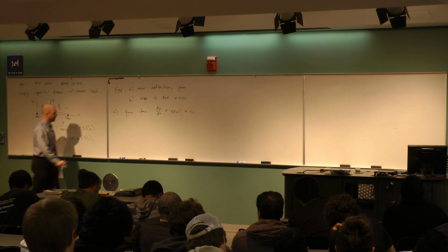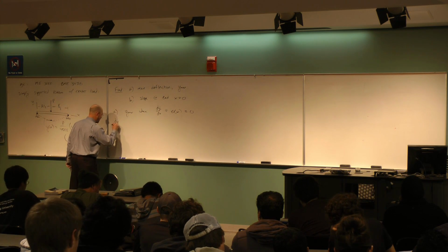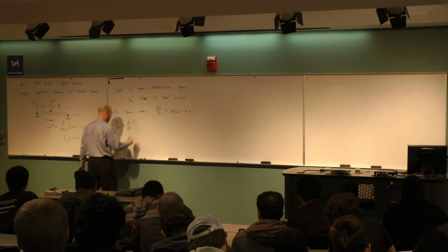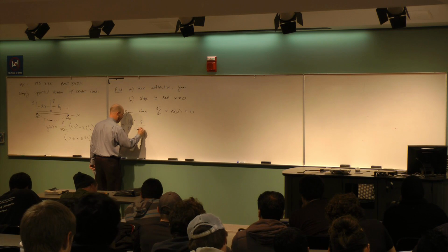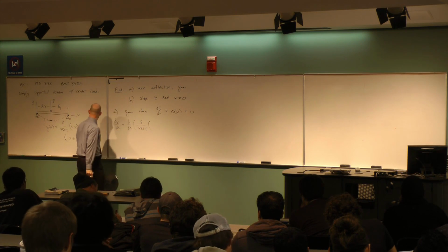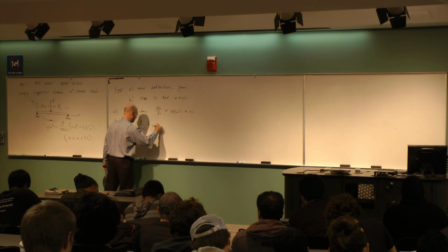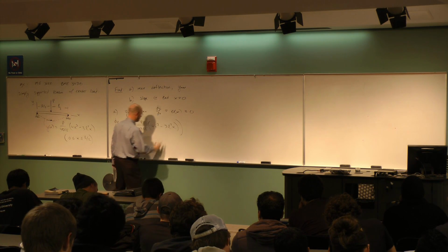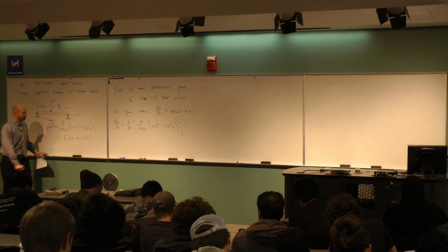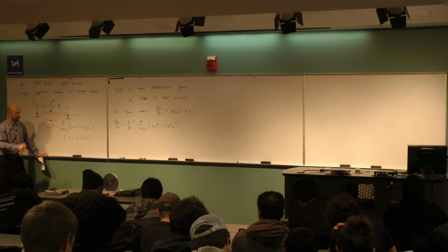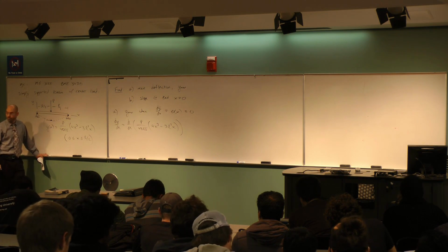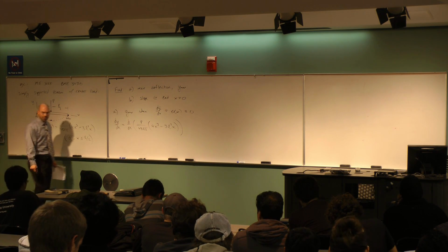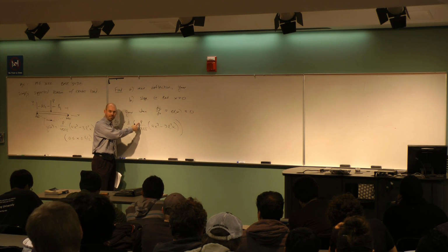So first thing I need then is dy/dx. So I want the derivative with respect to x of this entire guy here, P divided by 48EI, and then I've got 4x cubed minus 3L squared times x. So help me out here. What do I do with the letters out in front? P over 48EI. It's just constant, right? These are numbers. This P could be 100 pounds.